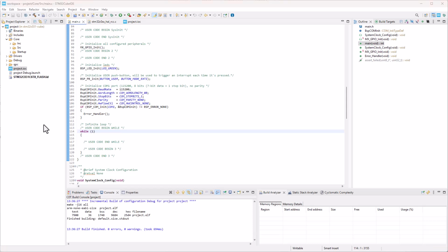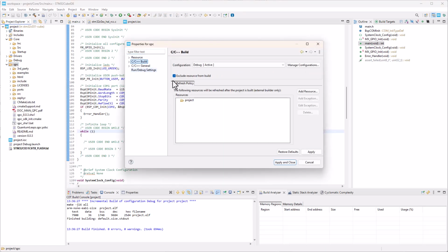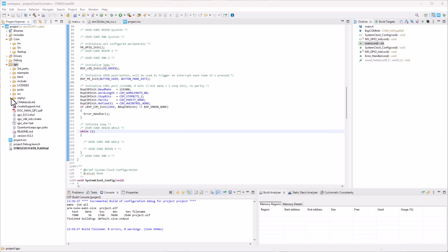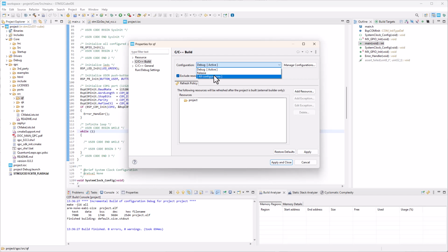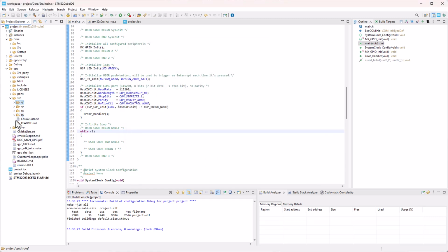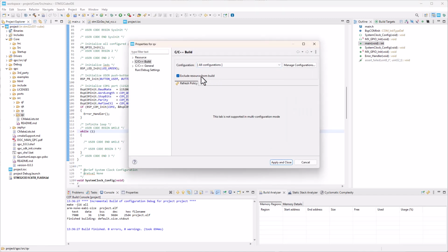Interestingly, the build does not compile any files from the QPC folder because this new directory is excluded from the build. So now you need to include the specific parts of the QPC framework in your build. For today's project, you include the following QPC subdirectories, being careful to apply it for all build configurations. src/qf, which contains the platform-independent source code for the active object framework and hierarchical state machines. src/qv, which contains the platform-independent source code for the non-preemptive QV kernel.